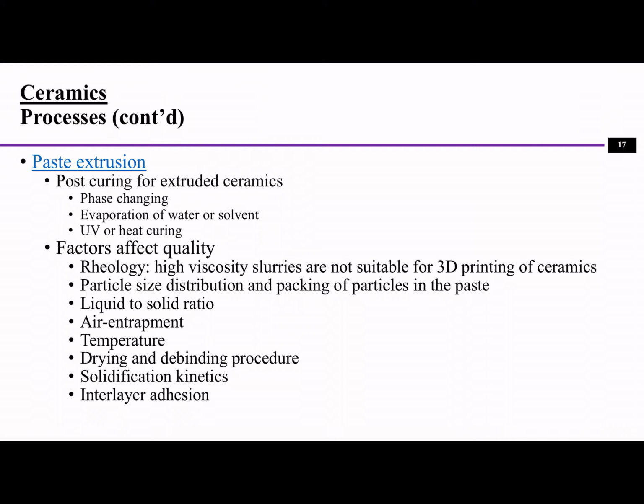So the packing of the particles is also a factor for the paste. Other factors are the temperature, air entrapment, drying, debinding procedure, and solidification, and also interlayer adhesion. These are the factors affecting paste extrusion.